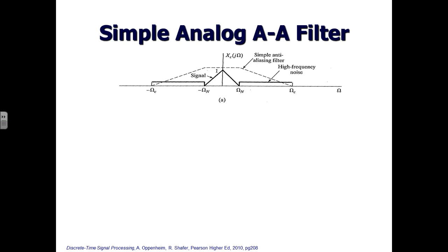Above that is shown a frequency response, or magnitude response, for a fairly low order anti-aliasing analog filter. So it's flat in the passband and the part that we want to keep, but notice it rolls off very gradually above the Nyquist rate, whereas we'd really like that to be much sharper. But because it's a low order filter, that's the kind of slow roll off that we get.